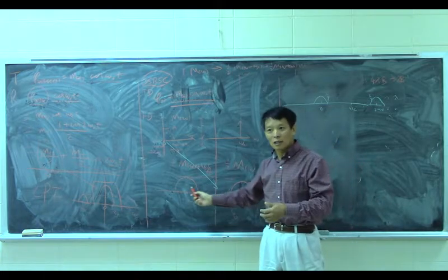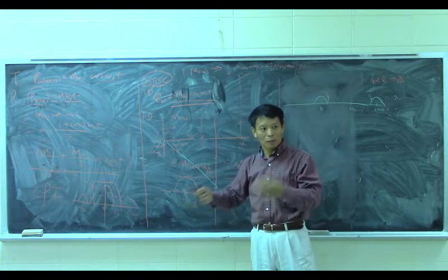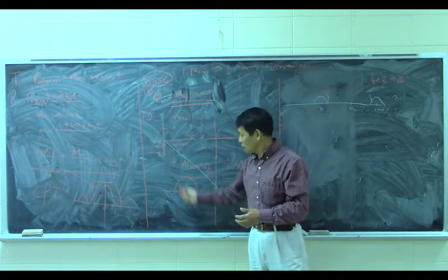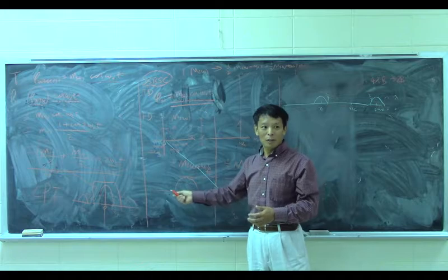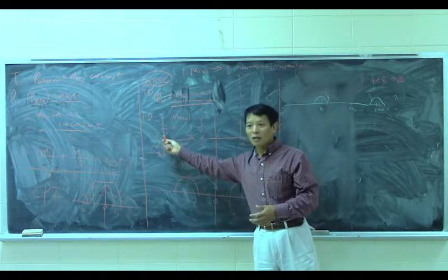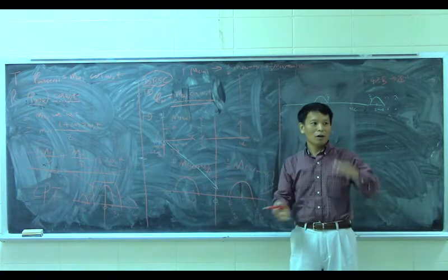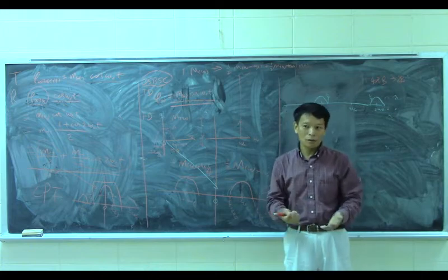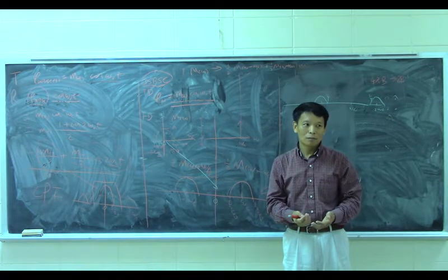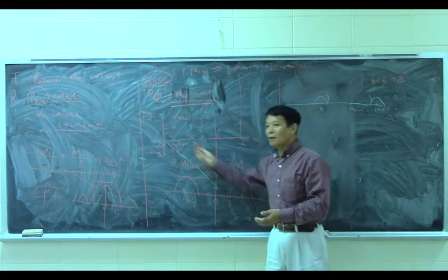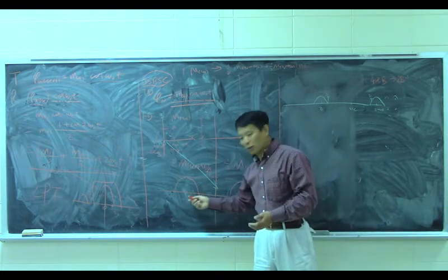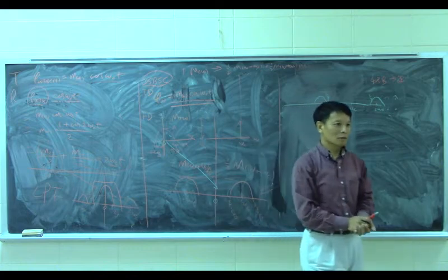And you need to do this to the left also, at the same time. So negative omega c, from 0 to negative omega c, also reduced to half. So you copy this one, you get two copies, and each copy is reduced to half amplitude. Make sense? So that one is easy to consider. This one, shift to the right and to the left, and reduce the amplitude.